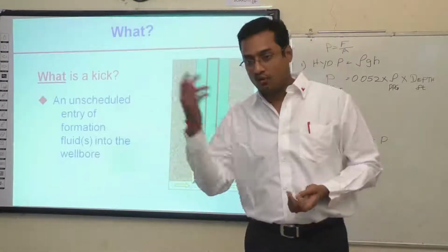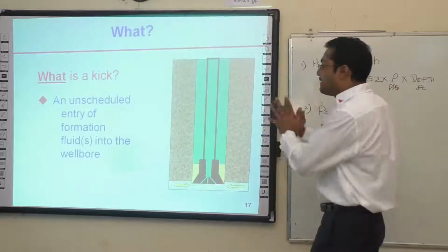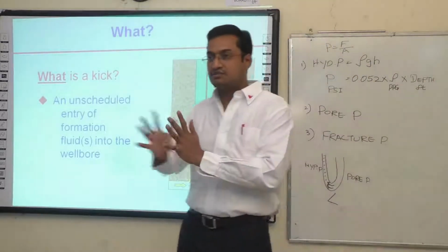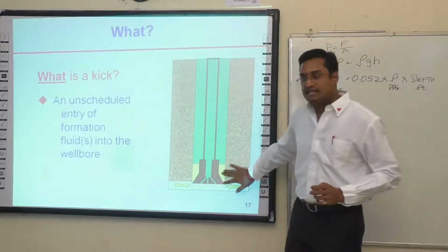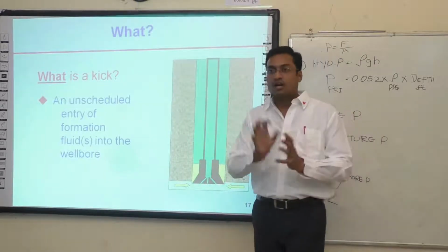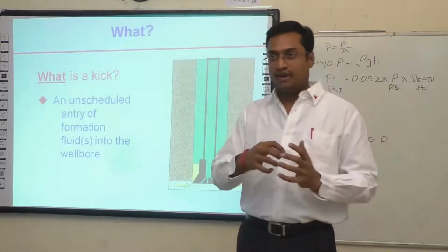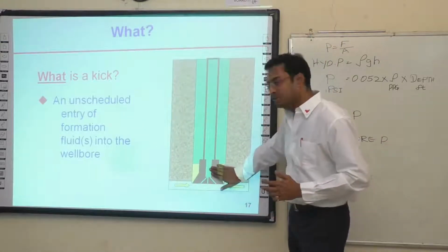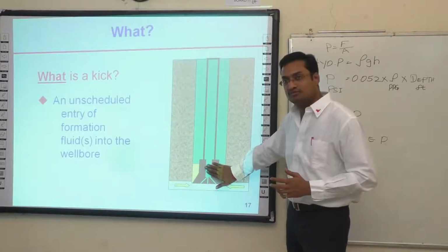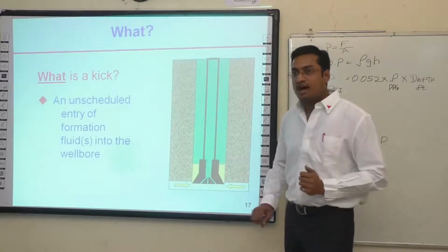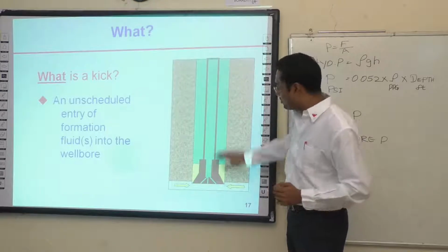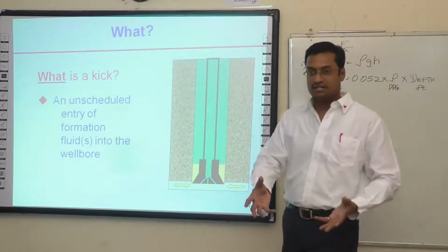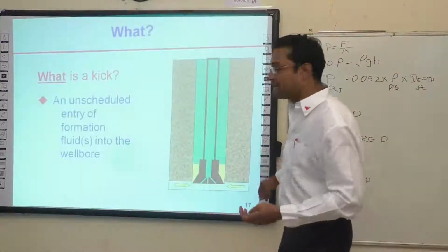So now, we will recap what we have studied in the last 5 minutes. What is a kick? A kick is an unscheduled or unwanted entry of formation fluid or pore fluids into the wellbore. For a kick to happen, the formation pressure should be more than the hydrostatic pressure, an underbalance condition. So a kick happens in an underbalance condition.